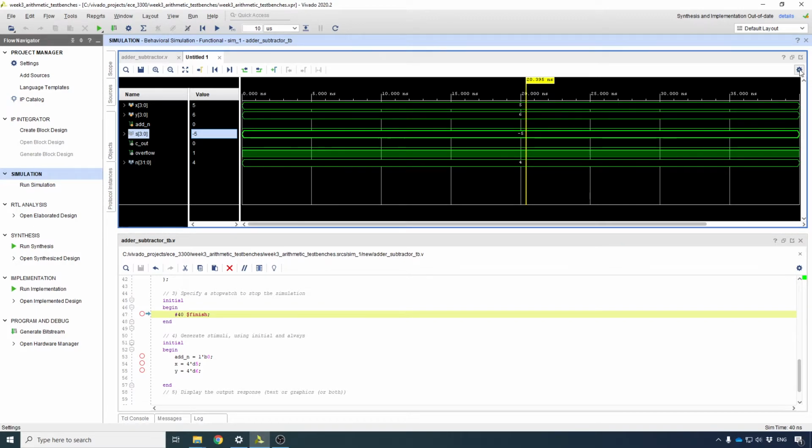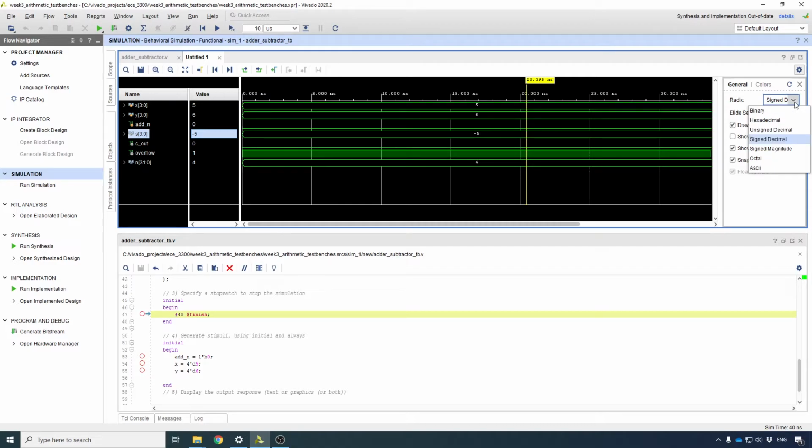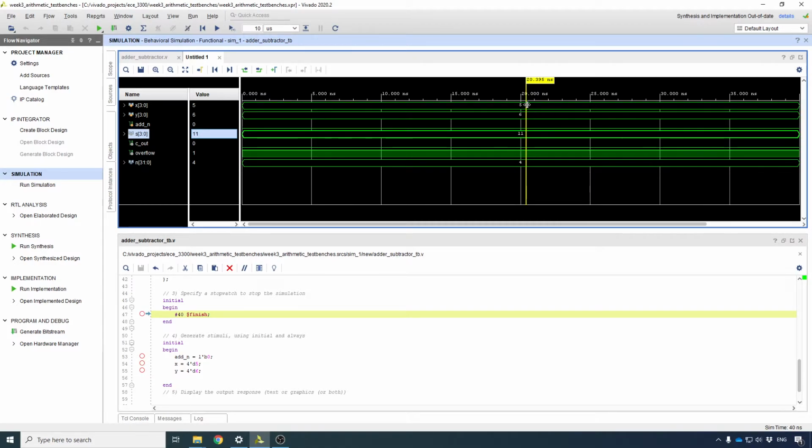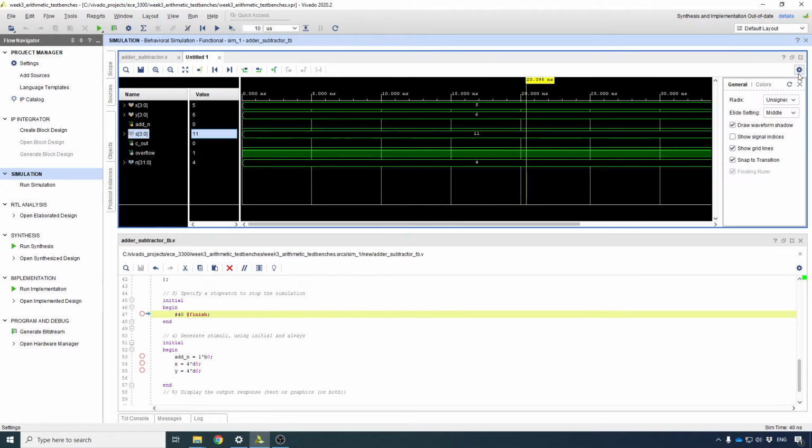Well, because probably the radix here is called signed. Okay, so if you actually go and do unsigned, you'll get that number. So 5 plus 6 is 11, that's unsigned. Okay, so that's perfect. Of course, because 5 plus 6 is 11, if you're dealing with signed numbers, that doesn't fit, so the overflow should run. So let's do that in here.